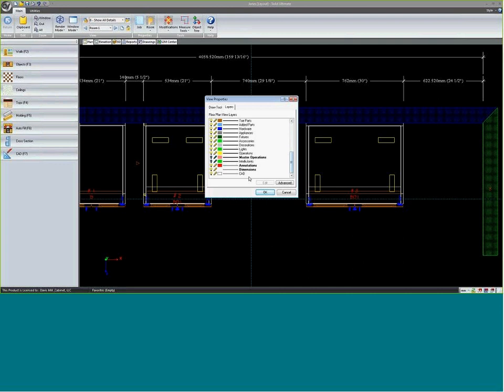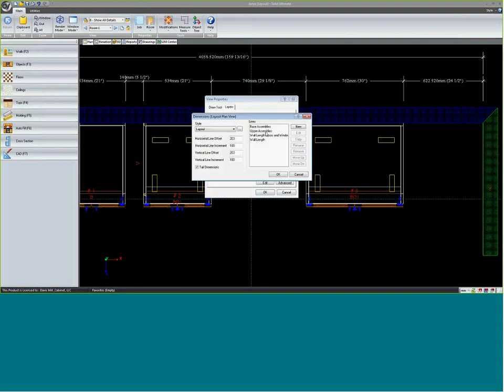One of the most common things to customize is the dimensioning. You can come in here, and we won't cover this too much in depth today, but you can edit the dimensioning, and I can edit different lines. When it refers to line, this is a line of dimensioning right here. This is another line. So if I'm in different views, different planar elevation or 3D views, I can customize how my dimensioning shows up and set it to a specific layer.